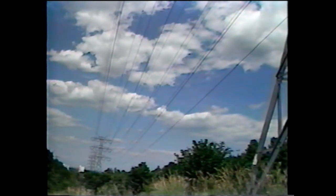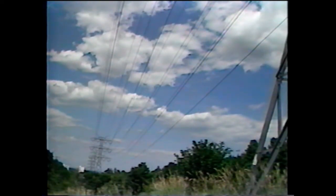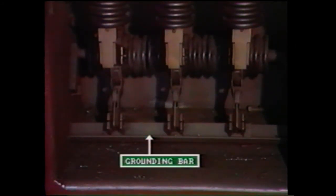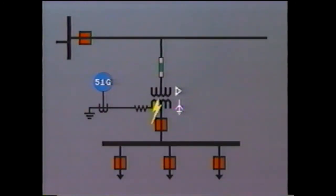Of course, on large, high-voltage transmission lines, this method is used extensively, but it is not so common on distribution systems. One method of initiating the trip is to have the protection relay trigger a spring-loaded ground switch. This will apply a solid ground to one of the lines on the high-voltage side.